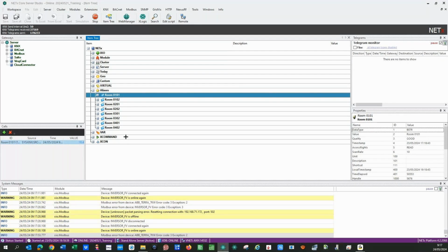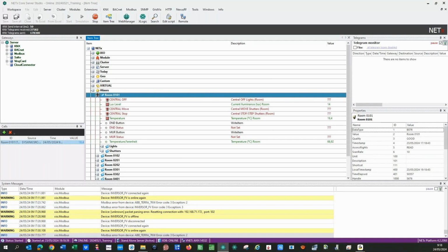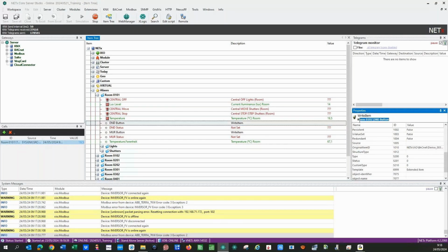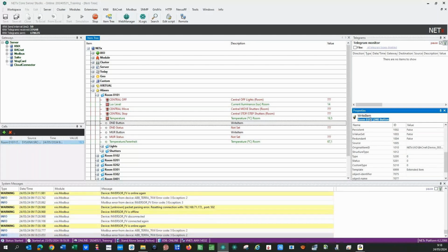In this case, a hotel as an example. We have mixed in the same folder things that come from KNX and elements that come from BACnet, where the original item is totally different. So we took this decision to take advantage of the aliases that the BMS platform gives us to structure these items also in terms of rooms. I will show you how to take advantage of this.